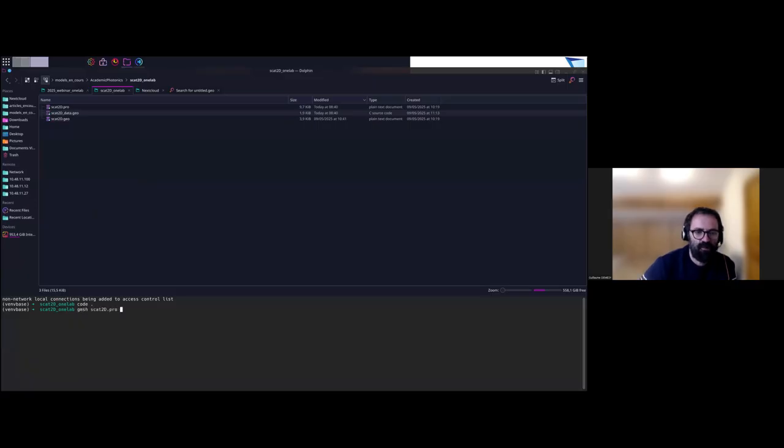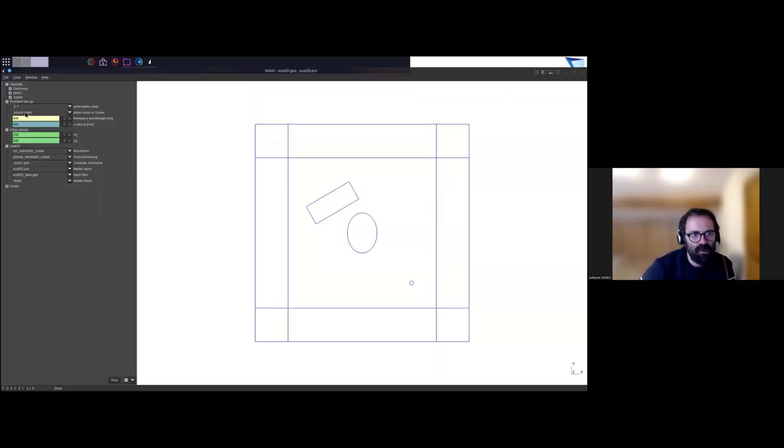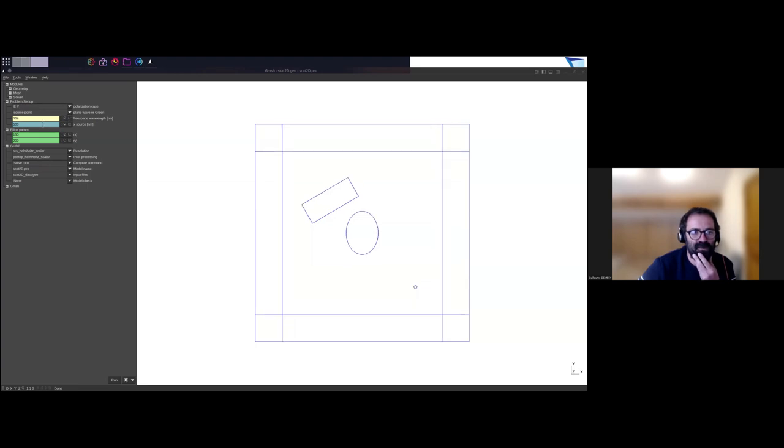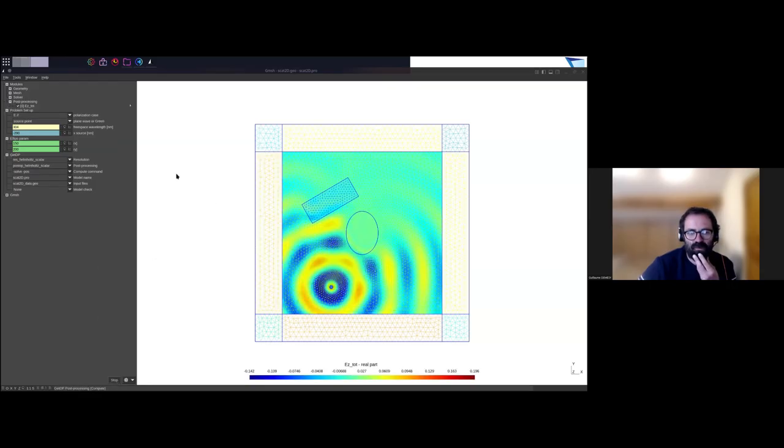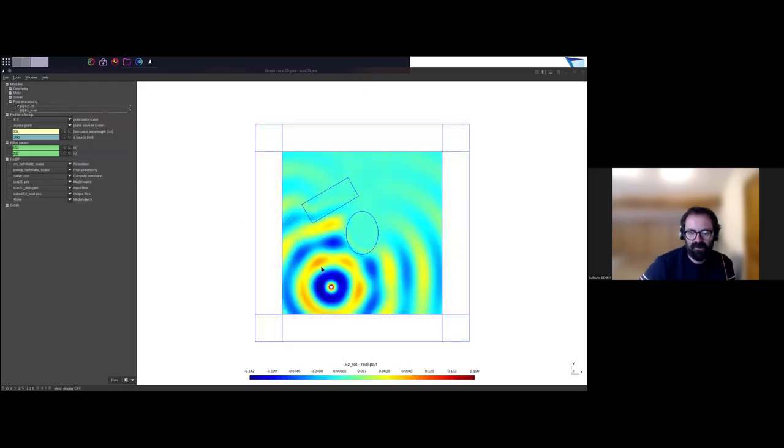And I can just reopen my model here. And now, as you can see, I can switch the polarization case, TE or TM, switch from a plane wave source to a source point, set the free space wavelength, change the position of my source point, etc. And I can just rerun the model, and you see that the total field is now modified accordingly.